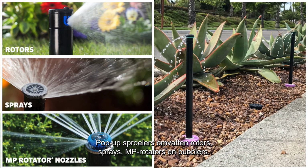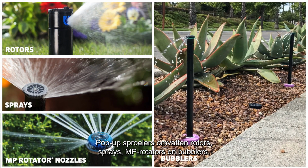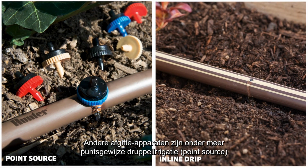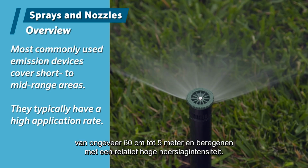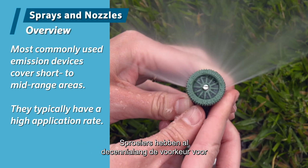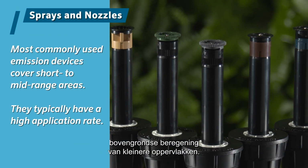Pop-up sprinklers include rotors, sprays, MP rotators, and bubblers. Other emission devices include point source or inline drip irrigation. Pro spray heads cover short to mid-range areas between 2 feet and 17 feet and apply water at a relatively high application rate. Spray heads have been the preferred method of overhead irrigation of smaller spaces for decades.